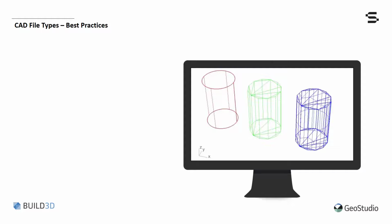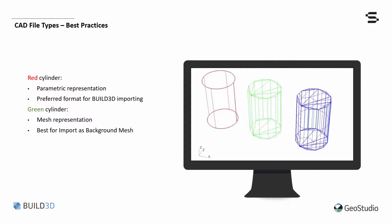The red cylinder is a parametric representation. It is an extrusion surface consisting of three parametric surfaces: the bottom, the top, and the curved side. This is the preferred representation of geometry in Build 3D. The green cylinder is a mesh representation of the surface. It contains 50 vertices and 32 faces. Build 3D cannot import the cylinder as a solid, but we will review it during the background mesh portion of this video.